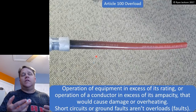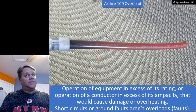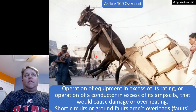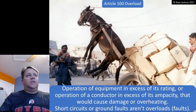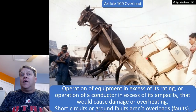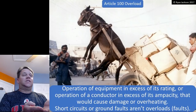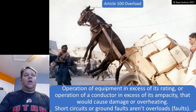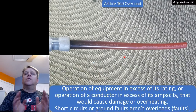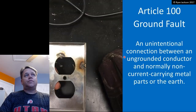Too much stuff on the circuit. In your bathroom, you plug in 6 curling irons and a hairdryer, you're going to have an overload. Operation of equipment in excess of its rating. This donkey here is only rated for so many boxes of whatever that is. That's an overload, right? Look, operation of equipment in excess of its rating, or operation of a conductor in excess of its ampacity. So that's an overload. That's one type of an overcurrent.